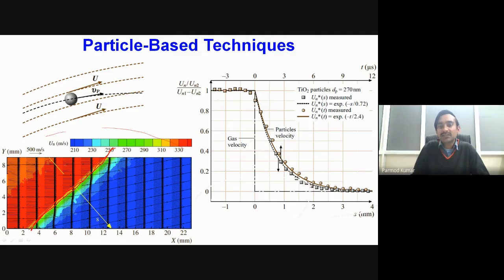Okay, so you can see on this corresponding graph, the velocity is presented in the normal direction, so this is considered as a direction normal to the direction of the shock. When the velocity is presented over here in the non-dimensional format, you can see this is the variation of the velocity. Here it is written, this dashed line is actually showing the variation of the gas velocity. You can see corresponding to the location S equal to 0 mm, we are having nothing but a sharp change in velocity of the flow field.